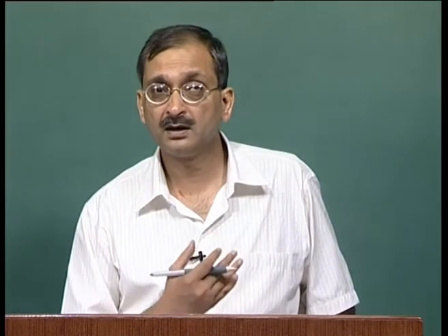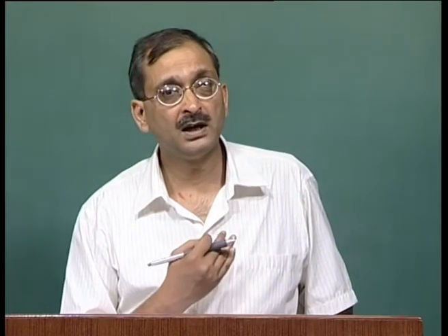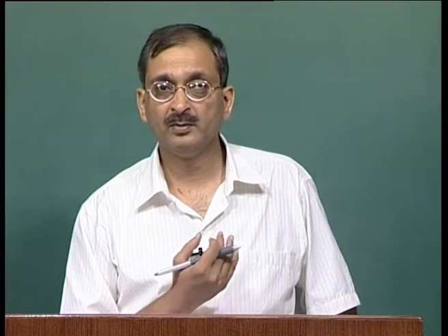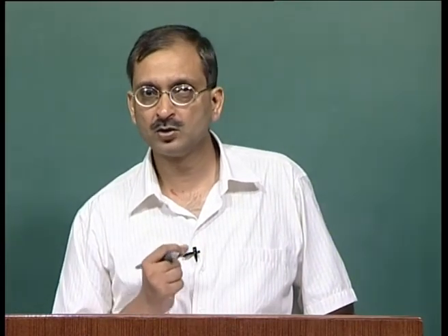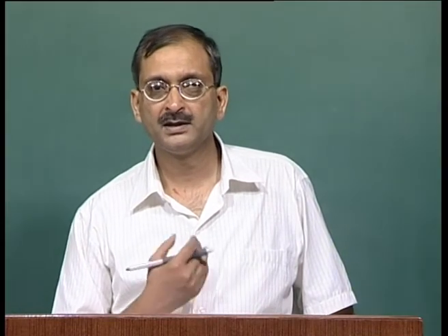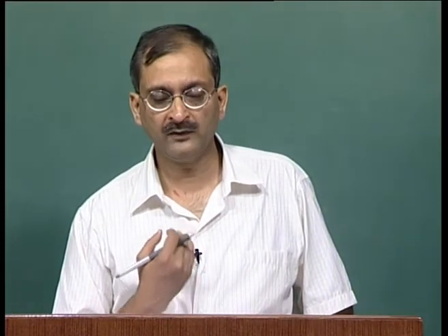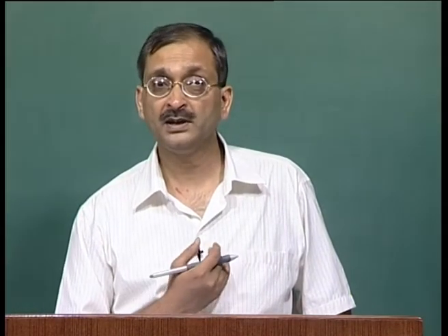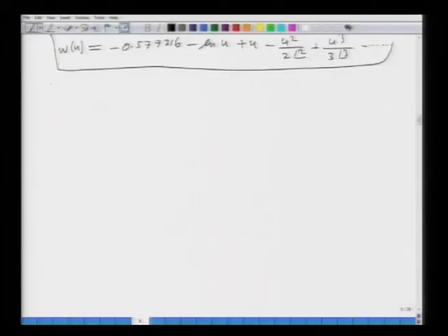So, if we can make certain observations in the observation well, we can use these equations, the solution which we have just obtained, and we can determine the value of the aquifer parameters, which will be much more economical. So, people suggest that the use of the non-equilibrium equation is much more efficient as compared to using the steady state equation for the determination of the aquifer parameters, and we will look at a few reasons for that.